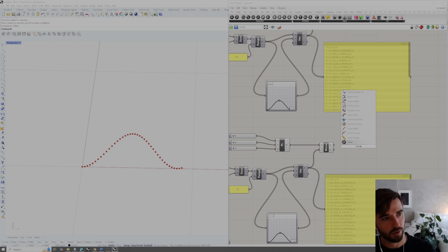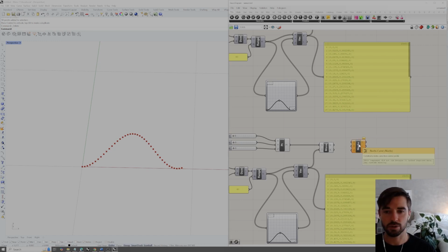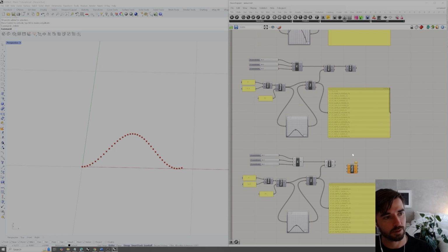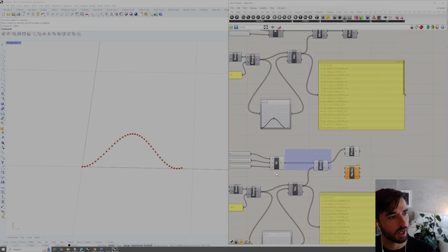Now, we can just type curve, and it's going to give us that input curve parameter. But what we want here is actually a NURBS curve. So if we select NURBS curve, then like our intro to curves from the Rhino video, if we plug in all of these polyline vertices into our NURBS curve, just to prove this, I guess I'll also make a polyline component again. So we'll keep this input as the input to our polyline. We can hide these previous points as well. So we'll turn those points off. And then I'm going to plug in this set of points to the vertices input to our NURBS curve.